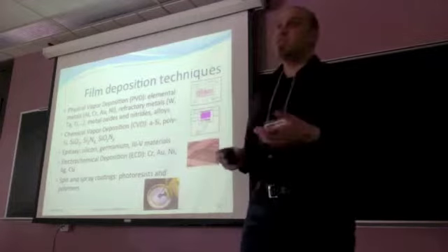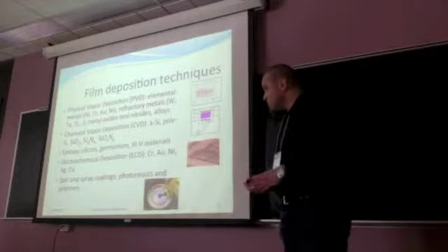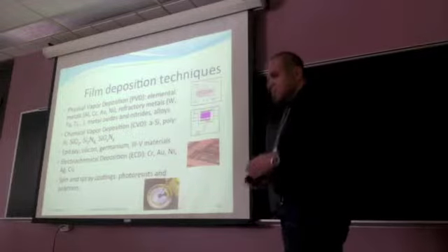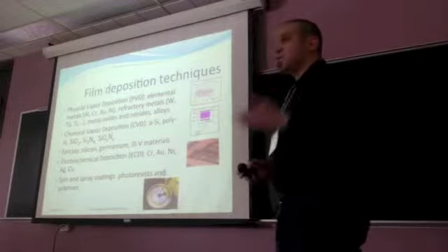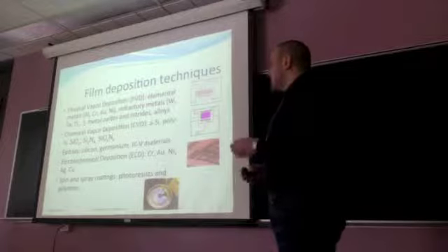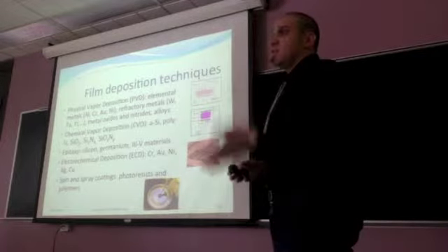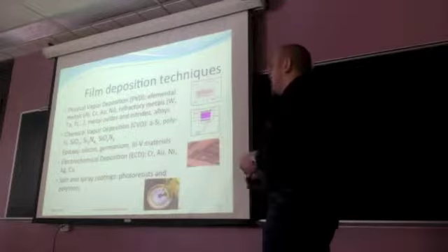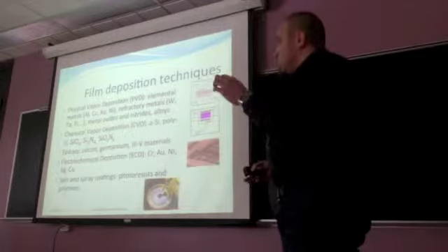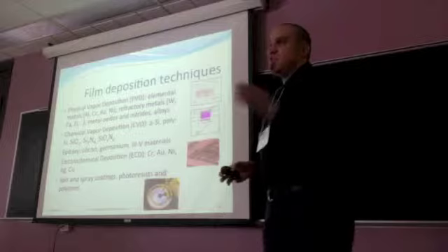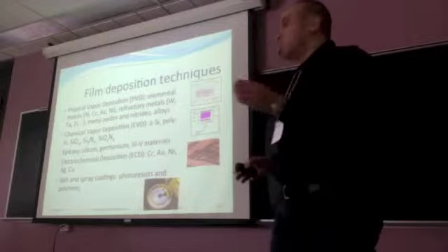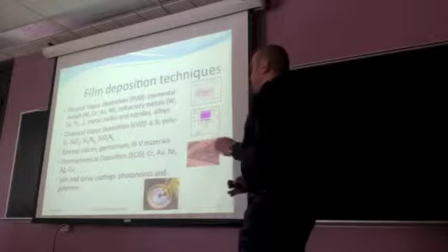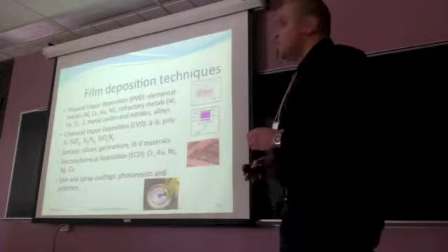The second category is chemical vapor deposition. In a reactor, source gases are introduced, and they react and decompose at the wafer surface at high temperature. The decomposition and reaction of these gases can be improved with a plasma at lower temperature. Thanks to CVD, silicon and its compounds can be deposited.